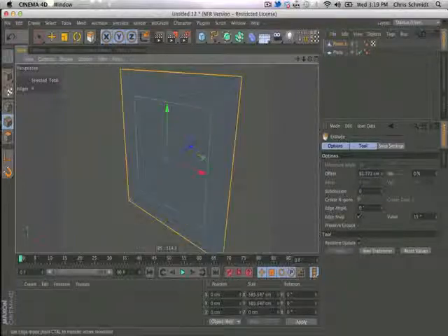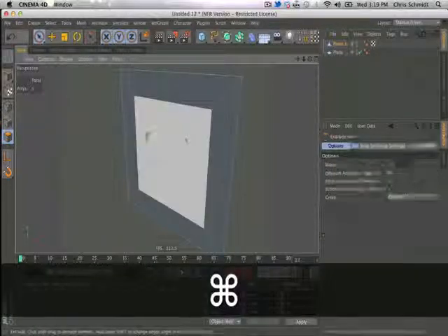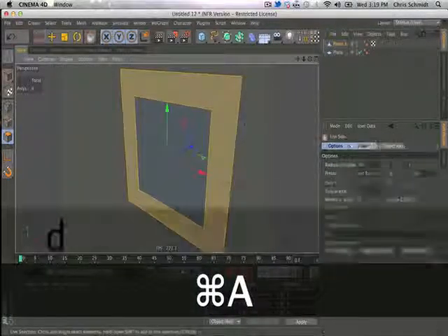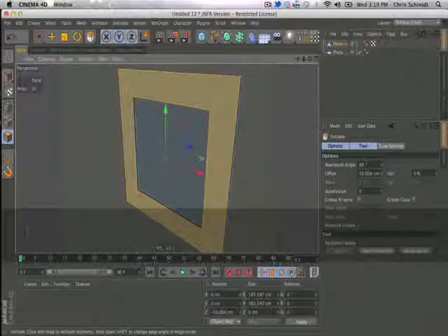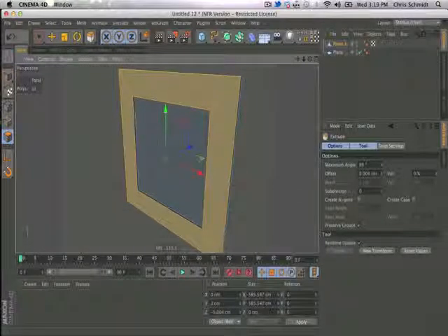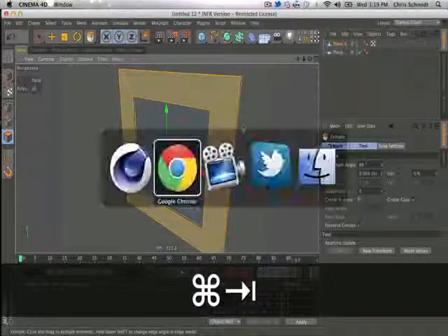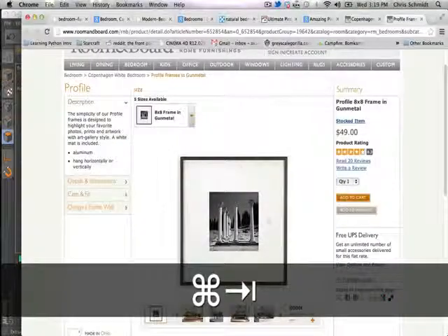So this will be the matte. And now I can maybe delete this middle polygon because I don't need it. Select all these, hit D for extrude. Now we can pull the matte out a little bit. We can create caps if we want the back to be in there. And now, so that's kind of this matte finish area.